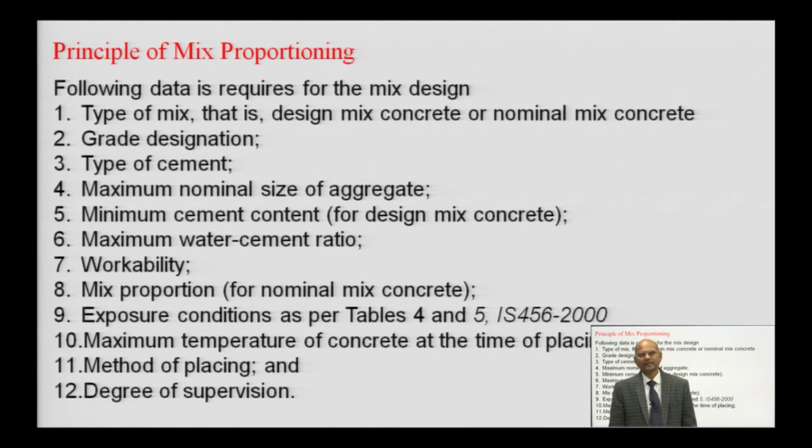Then we have grade designation. The grade designation should be known, what grade of concrete you need. That may range from M10 to M100. You may design, and even you can go for more than M100 grade concrete, but you have to refer to some special literature for that.